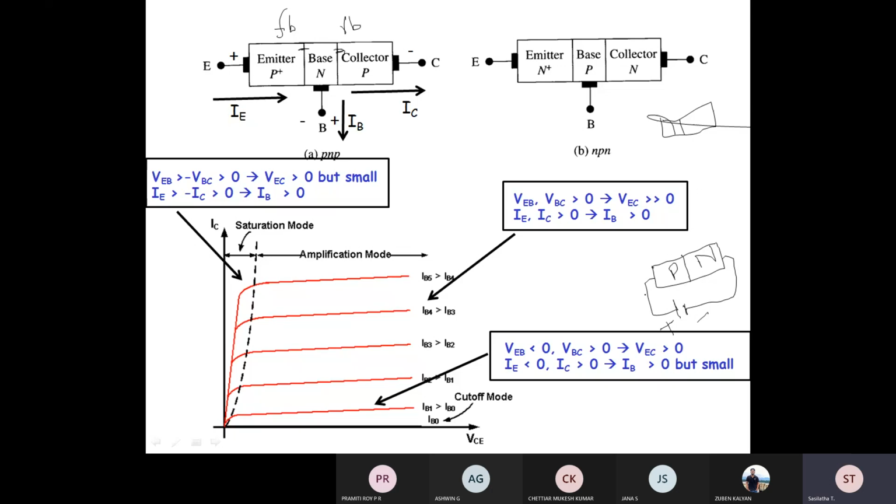It is not about potential or movement of charge carriers. Once it is connected, current flows; that we will explain. Understood what forward bias is? So connecting the positive of the battery to P type, and the negative of the battery to N type, this is what is called forward bias.